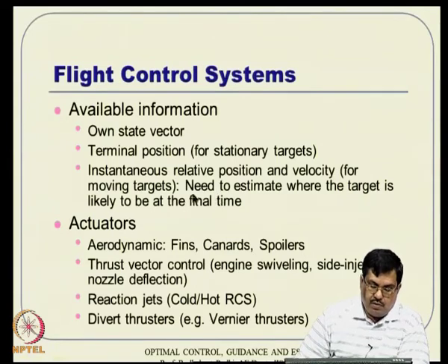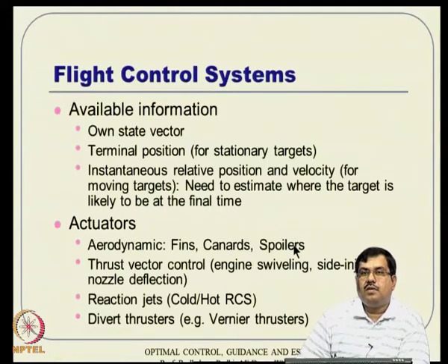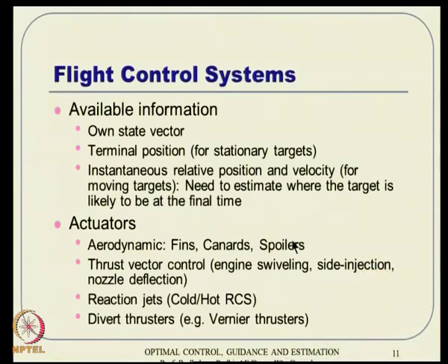Then there are actuators. So, we have various types of actuator. We have aerodynamically controlled actuator, such as fins, canards, spoilers and things like that, which are typically useful within endo-atmospheric engagement actually, okay, where you can generate lifts and moments and then manipulate that.